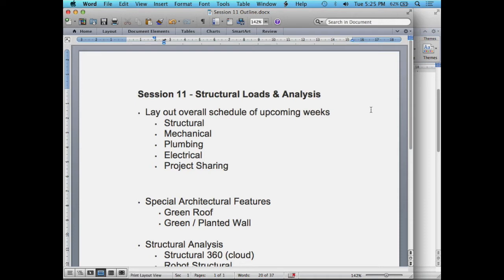How we actually model either a gray water system, where we're trying to reuse some of the water, store it, filter it, and repurpose it to handle flushing needs and certain needs where we don't necessarily need potable fresh water, as well as how we would design a water catchment system. So given the roof that you have on your building, you figure out how much rainfall you could actually capture, size a tank to do that, and then pipe that into the system to be used in conjunction with the city supplied water, the utility supplied water.